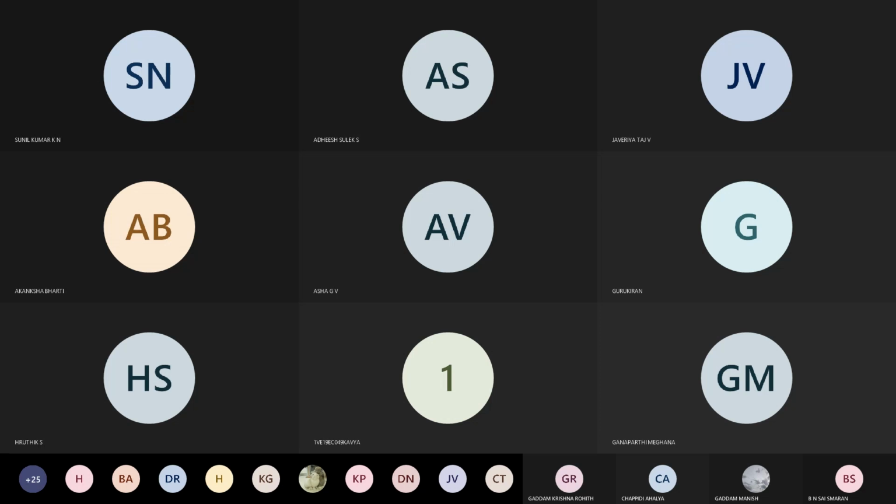So 3 plus 2 plus 1 is what? 6. 6 divided by 3 is what? 2. So you will be getting the average of these 3 inputs, which is nothing but 2. So you will be getting the value with a negative sign. The only thing is that you are going to have a negative sign. So what does the negative sign indicate? The negative sign is the indication that it is an inverting amplifier.